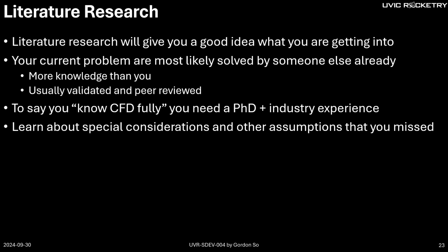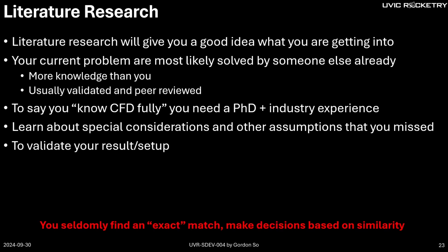And of course, you want to learn about some special considerations and typical assumptions that you may miss, that you may not think of. And the last thing is to validate your setup, because sometimes they will provide some kind of results that you can use. That will be excellent because you can just see if you set it up properly. You 100% will find a different case from your research, but make your decision based on how similar the problem is, and it will give you a within-ballpark result, which is good enough as a starting point.